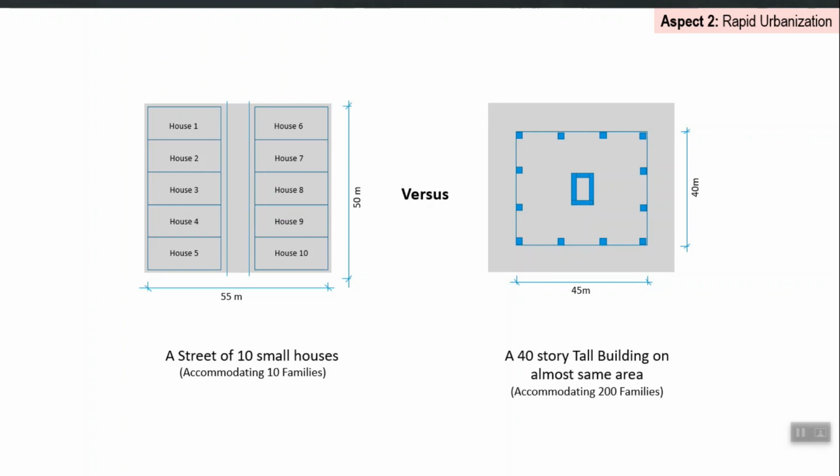Then that computer model is subjected to dynamic analysis at different levels of earthquakes, and that model can explicitly tell at what level you can expect cracking, at what level you can expect yielding, and at what level you can expect crushing, for example, right. So everything is clear. You can actually show the results of that nonlinear analysis to your client directly, which is something you cannot currently do, right, because that model will itself be telling you that this many beams will be yielded, or these columns will be cracked.